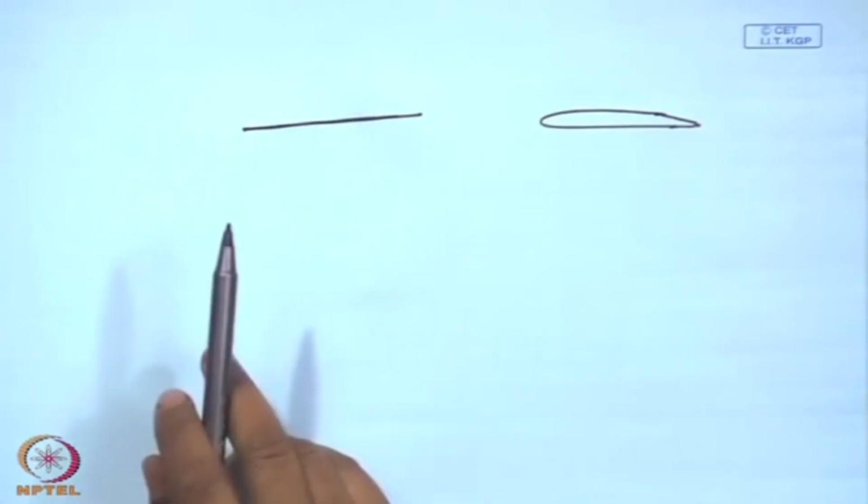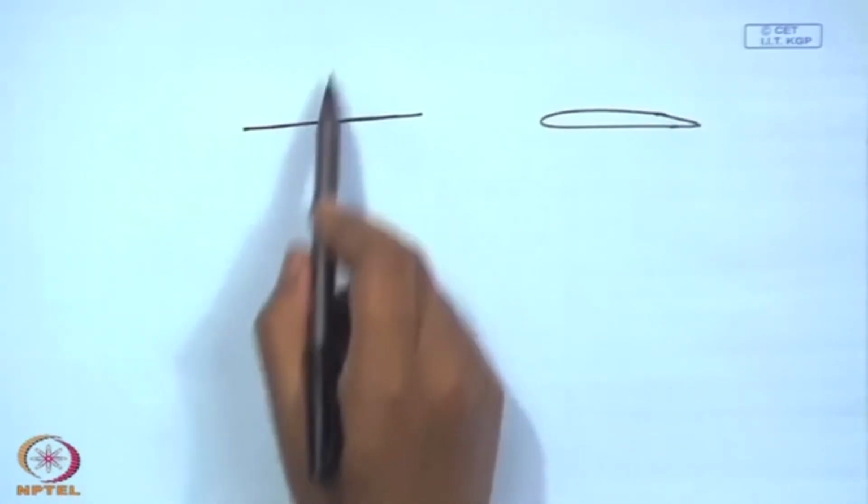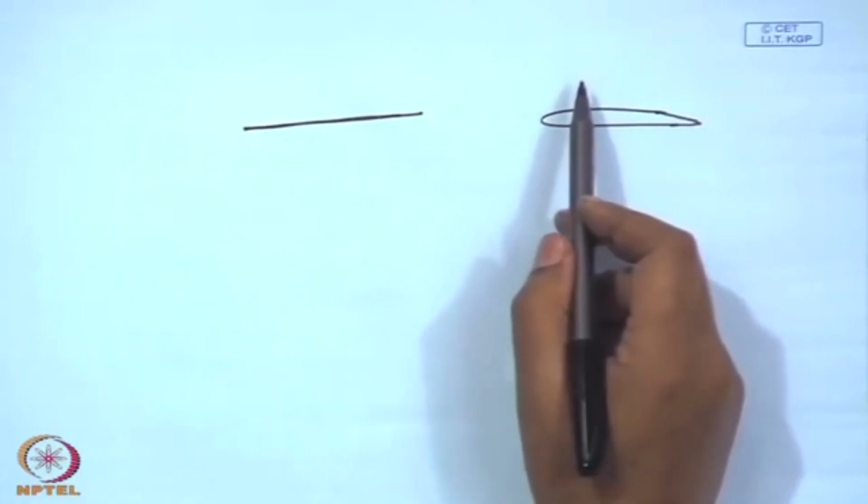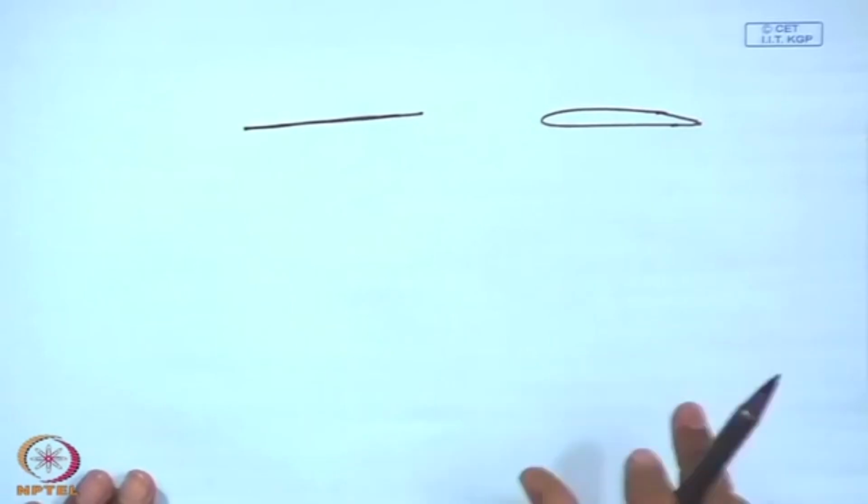Similarly, in the sideways direction, viscosity is trying to spread it in this direction, while convection is trying to carry it along with it. As we mentioned, the normal component of velocity being small, the convection in the normal direction is much smaller than the convection in the streamwise direction. So, even on these two sides there is practically an opposition between diffusive spreading and convective spreading.